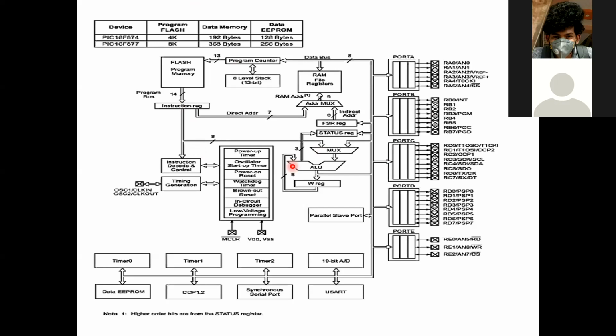We all have three operations. What are the three operations? Fetch, decode, execute. Always remember: fetching the instruction, decoding the instruction, executing the instruction. Decoding means, for example, if I give MOV, it will move from register to accumulator or according to the instruction. SUB, it will subtract the content. XRL, it will exclusive OR.